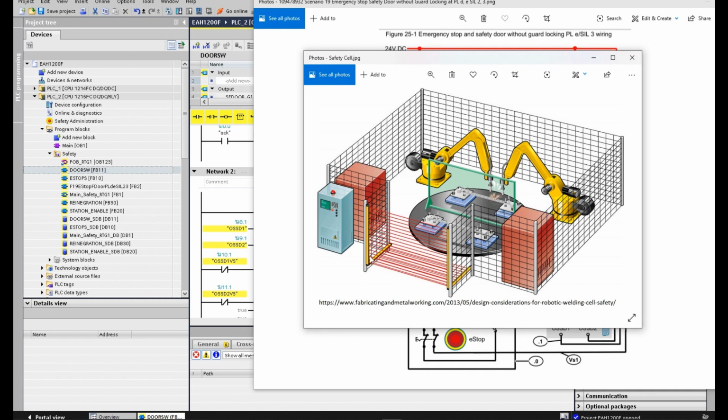And because this light curtain will also be involved in controlling this turntable, you can imagine when the turntable rotates, if someone broke the light curtain, the turntable must be stopped. Also, the tooling system towards the operator side also needs to be disabled by the light curtain. But if the operator broke the light curtain, the robot and the tooling inside the cell will not consider the light curtain. So that means usually the EStop is very straightforward, but the light curtain needs to involve some logic. So it will be a different logic to control this area.